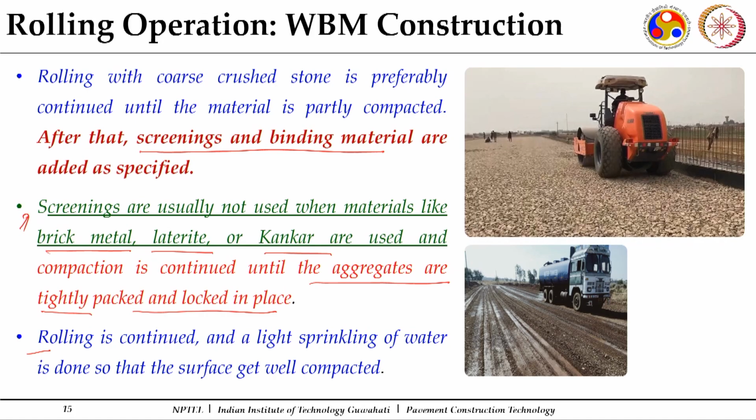In soft materials, they crush down, and the rolling is done along with a light sprinkling of water, so that the fines created by these soft materials get further packed in a good manner to give you a good desired surface.